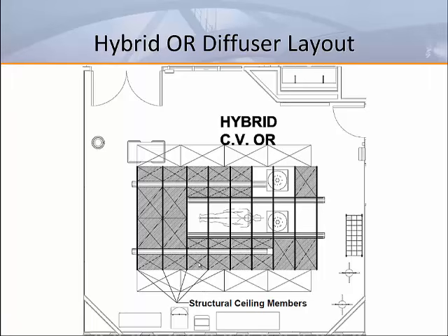This is close to 33 air changes per hour, which goes above the recommended 25. However, it must be done in order to meet the minimum requirements of 170 for the non-diffuser usage area and the minimum velocities within the space, or the minimum average diffuser velocity.